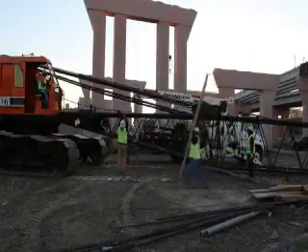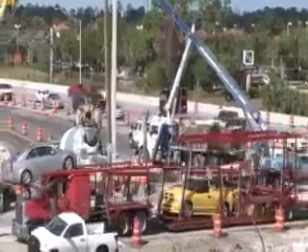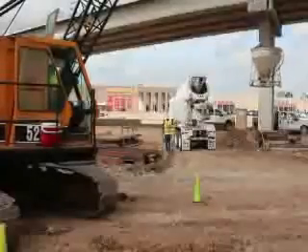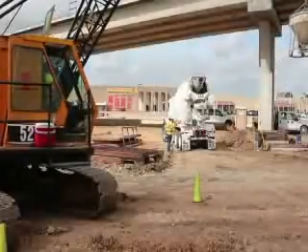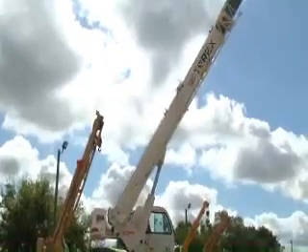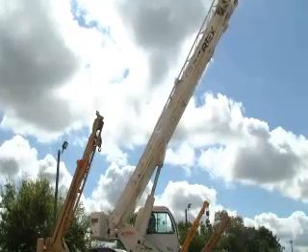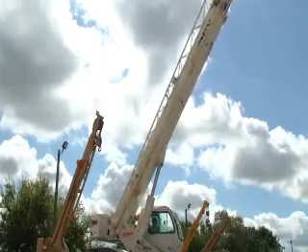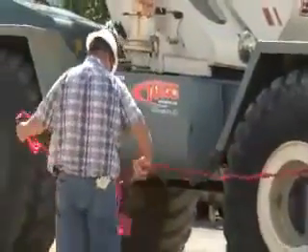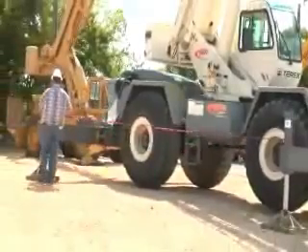Another major hazard when working around cranes is being struck by, caught in between, or crushed by the crane's moving parts. A crane's rotating superstructure can injure a worker who enters areas in which the crane rotates. Employees can be struck by the crane or crushed between the crane superstructure and another part of the crane or another object. Control lines, warning lines, railings, or similar barriers must be erected to mark the boundaries of the hazard areas.